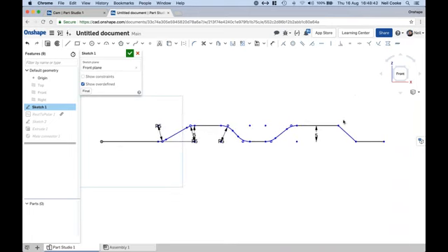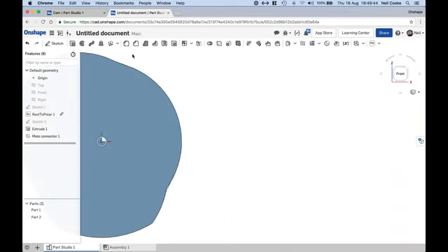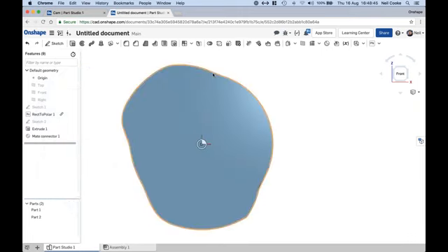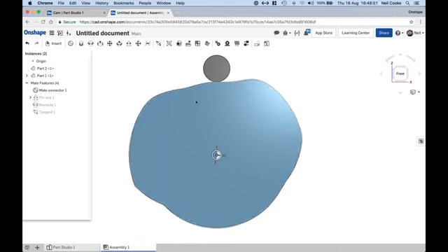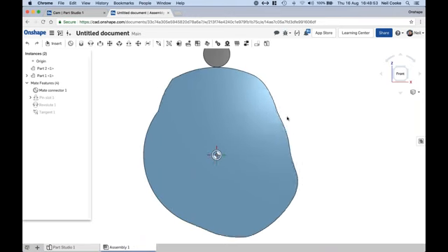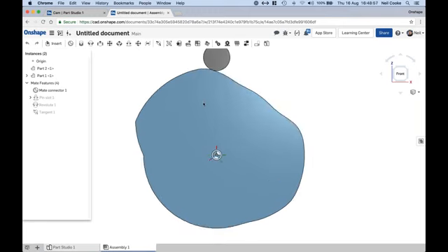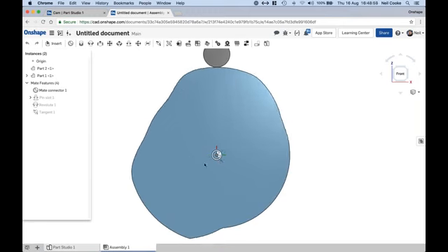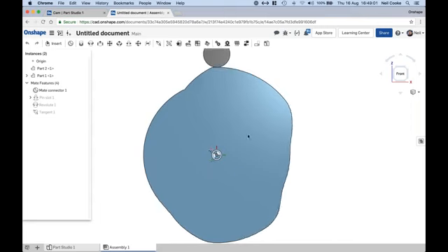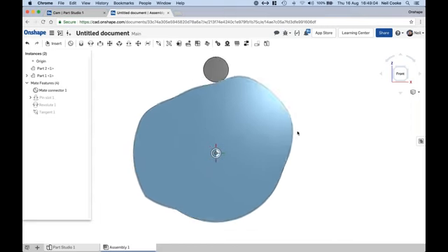Okay, that's okay. I missed a couple there, no big deal. So that's going to rebuild proper arcs within your profile. So now when you come to the assembly, you're going to make sure that there are no positions where that follower actually has more than one solution. So then you're going to get a lot better following on from the cam.